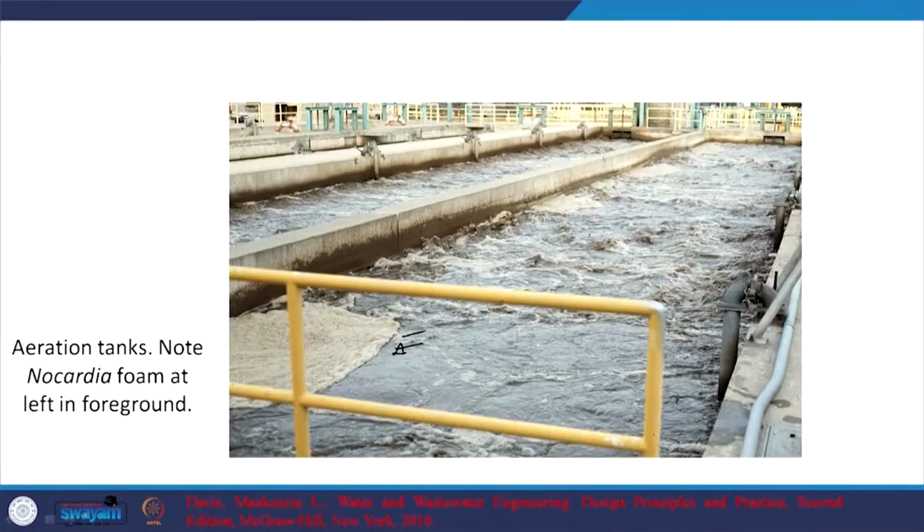relatively hydrophobic. Hydrophobic means they don't want to stay in water, so they would like to stay in the gaseous bubble, and they will lift up, and this is what you see here. In severe cases, you will have a lot of such Nocardia growth, and you will have foaming that's going to go out of your secondary sedimentation tank.